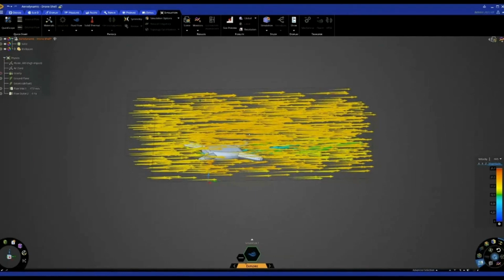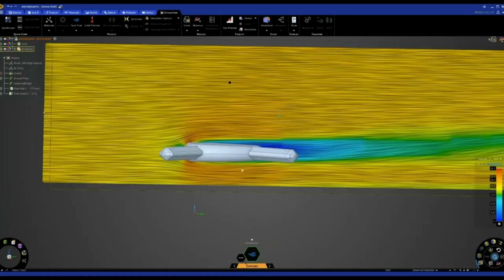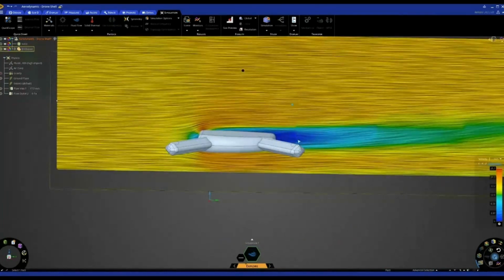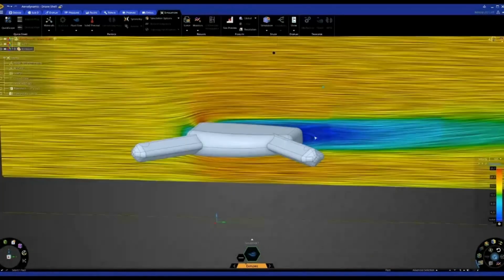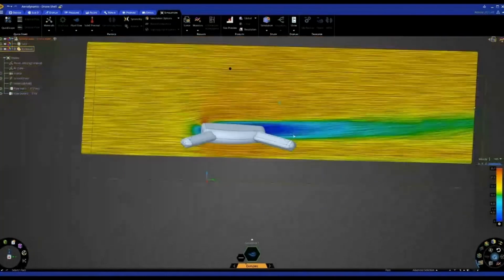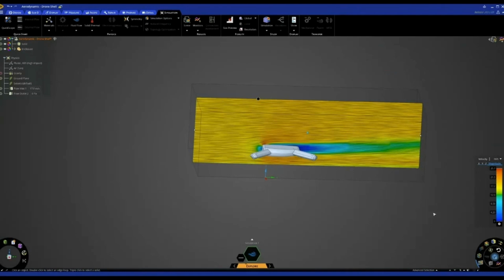So now that's complete, we can start to look at our direction field, and straight away I can see probably a smaller separation region for sure. Again, maybe less turbulent flow as well around the exit area. So you can straight away see an improvement from going from one design to another. So that's all the evolution as the design goes along. We can simulate as we go and see those improvements, and obviously we can also validate them with the actual results themselves. So that's just a quick example of external fluid flow on our drone.